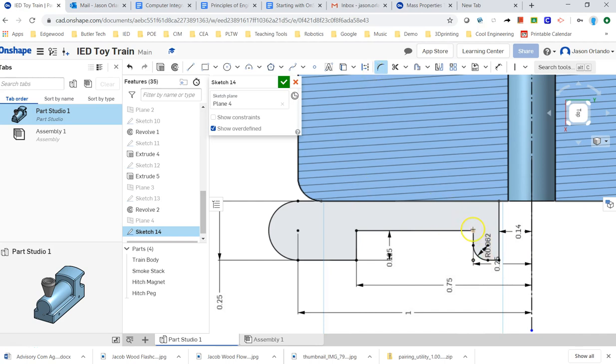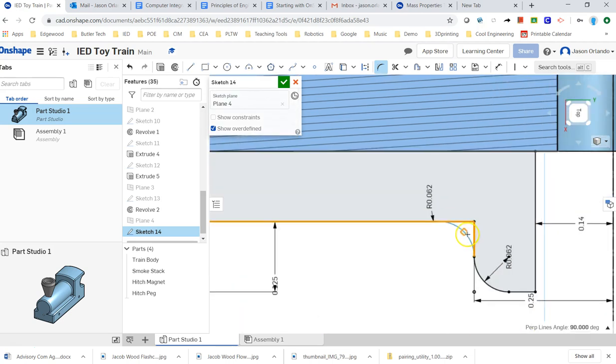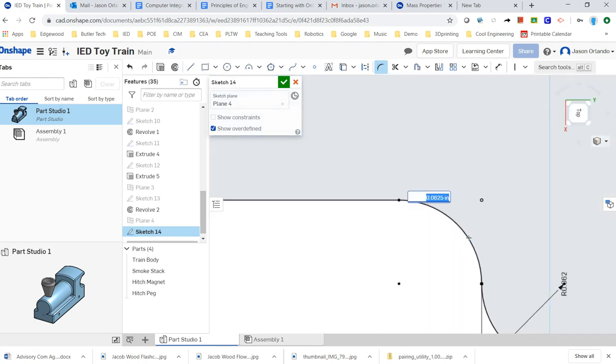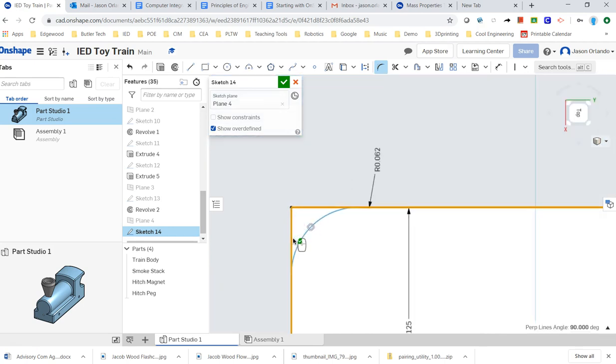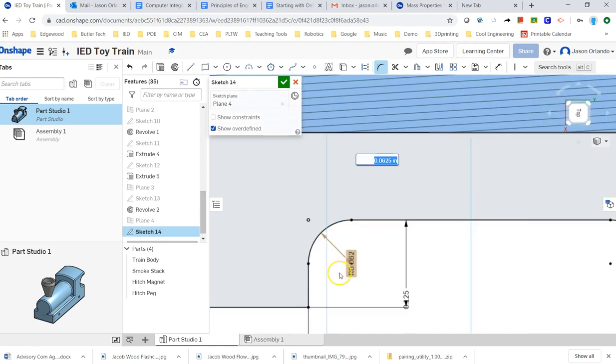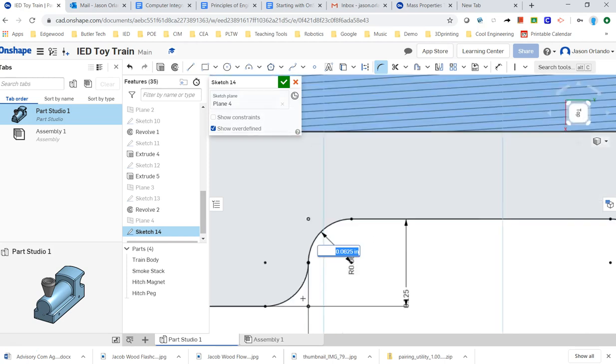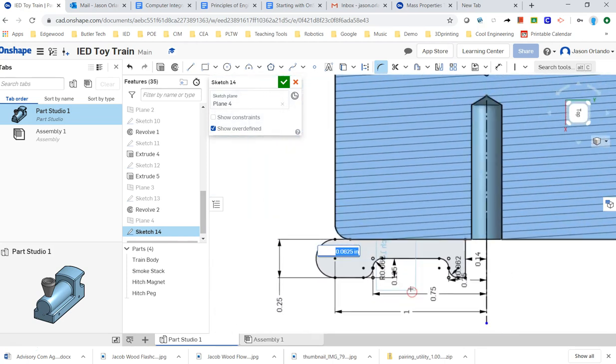So my fillet tool is still on. I'm going to grab the next. I can choose the 2 lines. Okay, and it's showing me a preview here, and you see I get a little icon that shows my mouse with a little green check, saying, hey, click it if this is good. Yep, it's good. So I'm going to left click and it applies it. So I'm going to come from this line to this line. I'm getting a preview. That cursor is giving me, again, the green check on the left mouse button. Yep. And then we're going to go from here to here. And that looks good. I think I've got the major outline of my wheel completed.